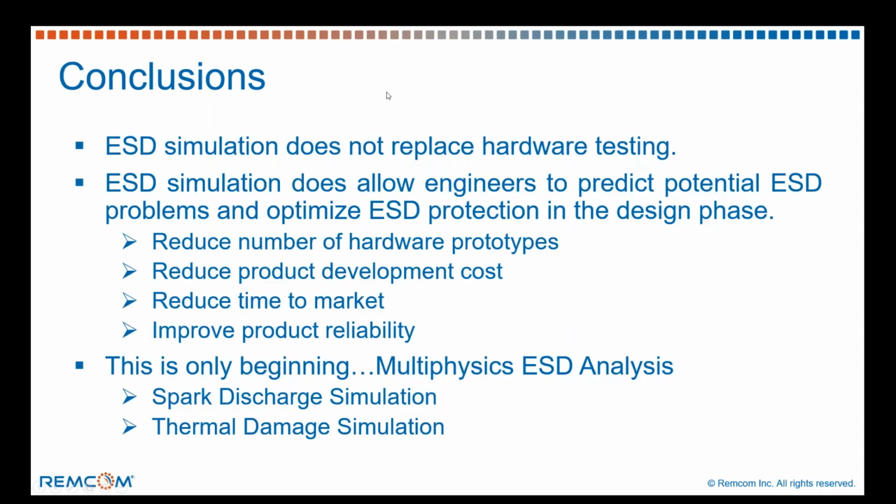Okay, I hope that got everyone excited to run off to their computers and do some ESD simulations. Just a couple of conclusions to state here. First and foremost, ESD simulation does not replace ESD hardware testing. That's still a step in everyone's manufacturing procedure that they are going to have to do.